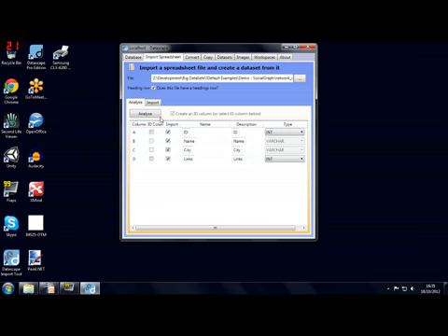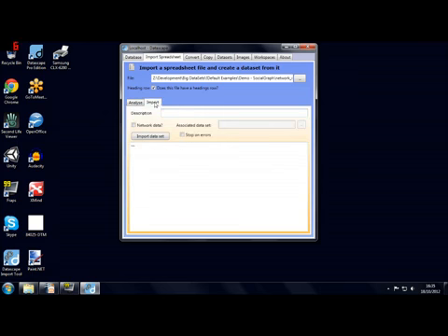And here it shows the fields that we had in the data. We just need to set the type for each of these, so we know that's an integer and that's an integer. If we want to here, we can actually get Datascape to generate its own ID for each of the individual rows. In this particular case, because we know the IDs are unique and they're important to the system, we're going to tick the box that says we want to use this ID column. And then we're going to go to import, give it a name, test network nodes, and click on import data.